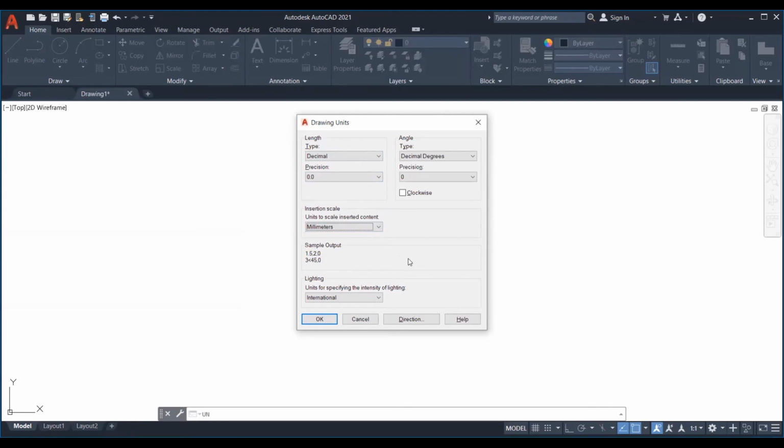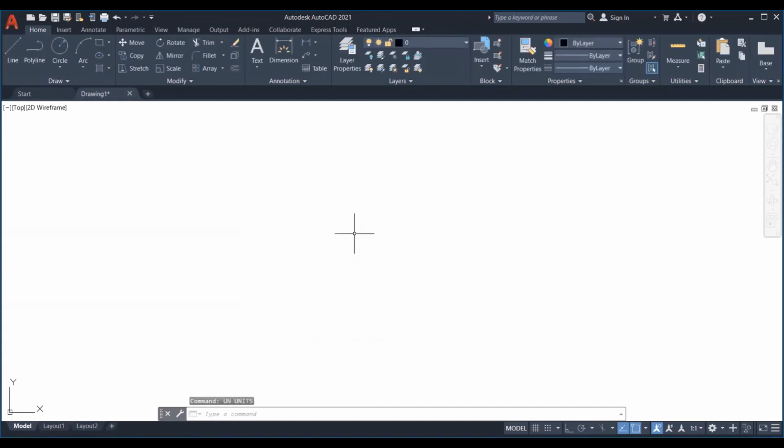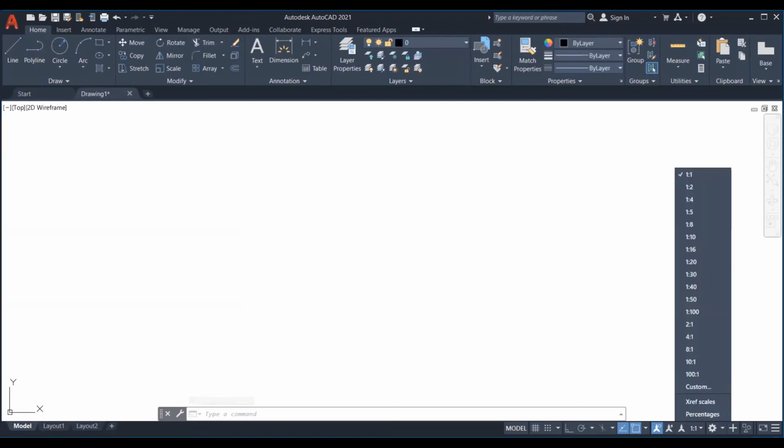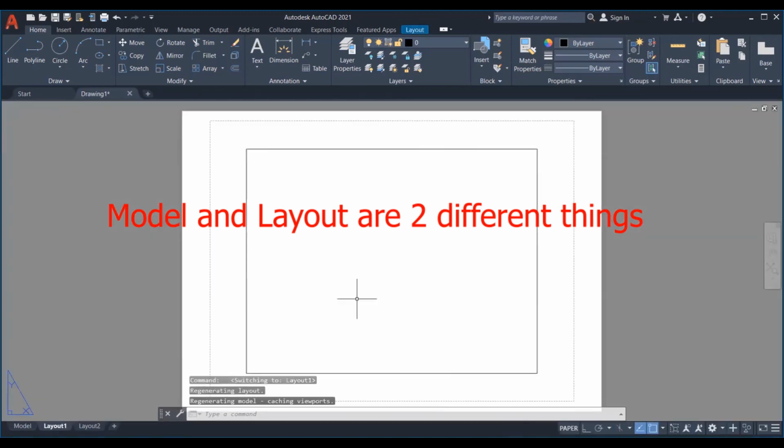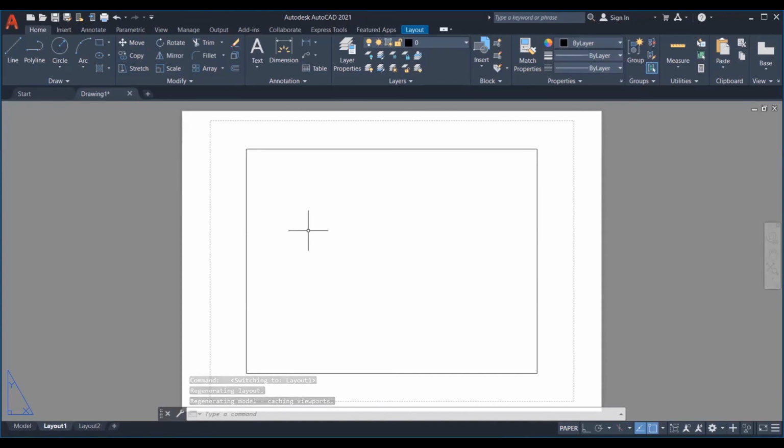Tip: if you change a setting for the unit display or any other setting, you can save the settings in a drawing template file. Otherwise, you'll need to change the settings for each new drawing. Model scale. Always create your models at full size, 1:1 scale. The term model refers to the geometry of your design. A drawing includes the model geometry along with the views, notes, dimensions, callouts, tables, and the title block displayed in the layout. You'll specify the scale for printing a drawing on a standard-sized sheet later when you create the layout.